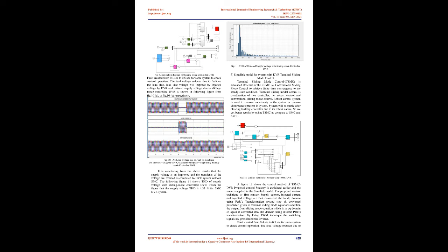2. Simulink model for system with sliding mode controlled DVR. To reduce the voltage THD, the system is simulated utilizing an SMC algorithm. The supply voltage is restored with SMC DVR. The proposed control strategy is explained earlier, and the same is applied in the Simulink model.